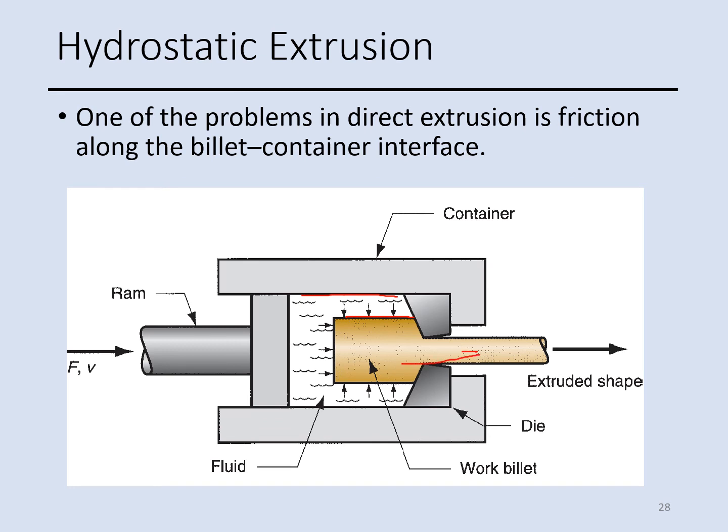this part can be created with a cross section with the shape of the die orifice. This way, there is no friction inside the container, and the friction at the die opening is reduced. Because of that, the ram force is significantly lower than in the direct extrusion process.